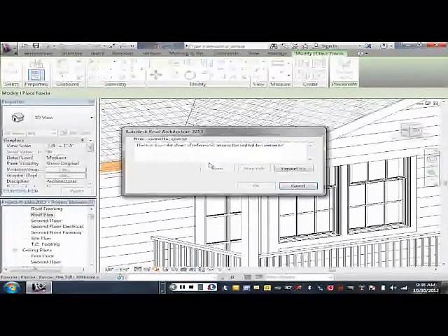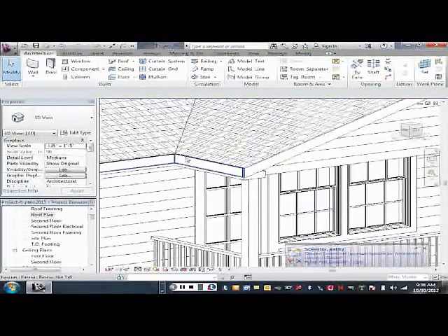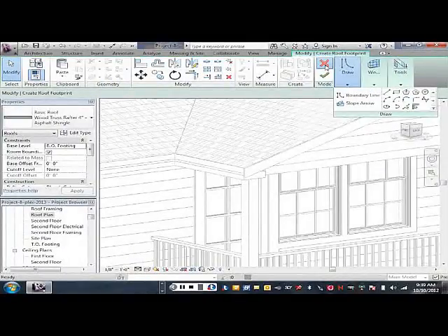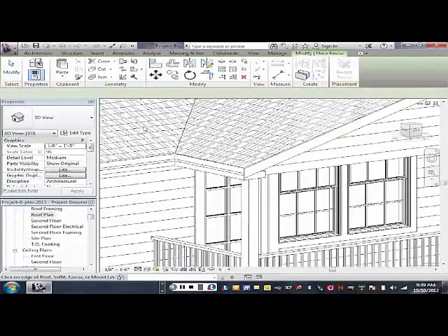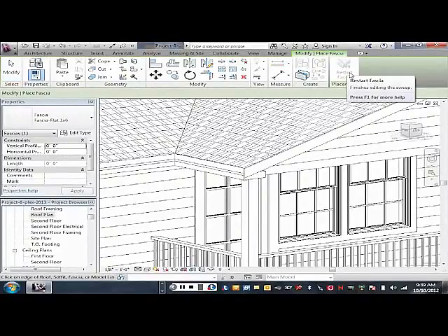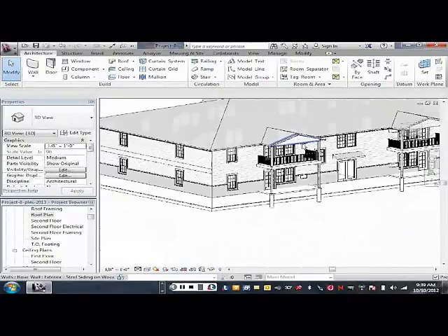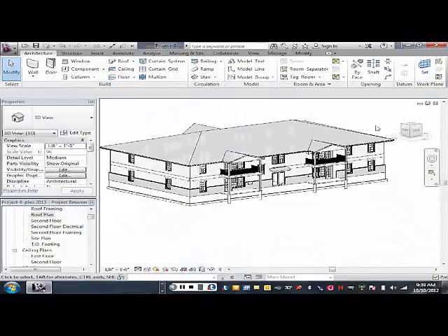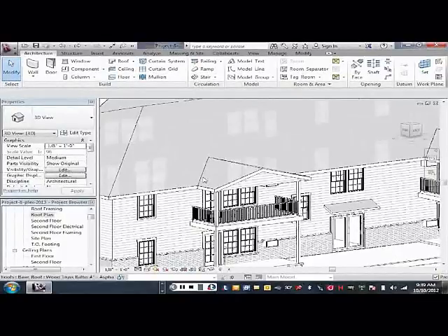When it doesn't work, you can always, you know, delete it. And then I could click on this one. Yeah, now my restart is not there anymore, and I can't restart. So you have to kind of make sure you do it all in one sequence. You can stop and restart again, but you can't stop completely and restart. Okay, so now I got my old fascia back on there. So that's how you put fascias on.